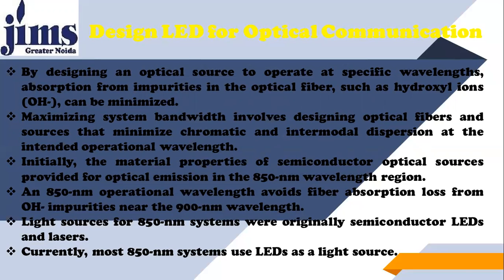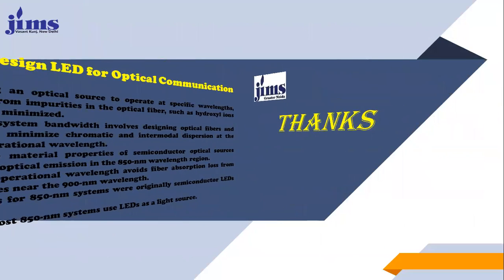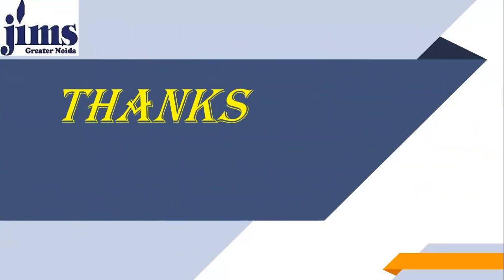Currently, most 850 nanometer systems use LEDs as the light source, for normally 90% of 850 nanometer wavelength. If you want 850 nanometer wavelength light, most probably you use light emitting diodes, or LEDs. So this is all about optical sources.